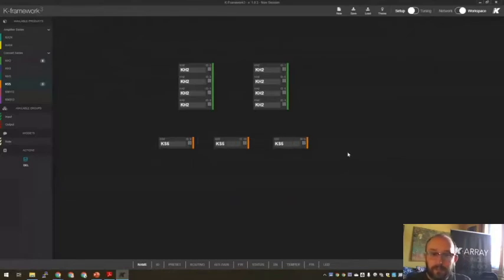Then, apart from a few operations, more or less everything in this software is done via groups. So you need groups to do EQ, volume, delays, etc. That's very important also to manage properly the beam steering, considering that all our line arrays, the Mugello and the Firenze, are able to work with beam steering with our technology. It's obviously fundamental that you tune an EQ and modify just the cluster as a unique unit.